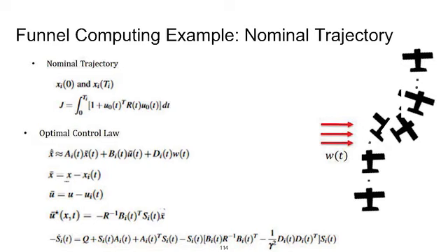So a standard way to do that is to have a cost function and create your optimal trajectory. This cost function basically mirrors an LQR controller. By solving all these equations, which is a pretty standard process, you get a controller that tries to bring you back to your nominal trajectory, and so you get back. You're happy. But you don't have any guarantees just with the controller. You don't have any guarantees on how far you can get pushed, or on where your system can be pushed to.